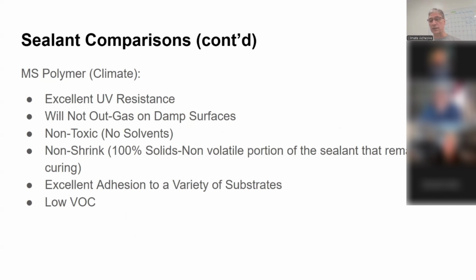So 100% solids just means the solids are just the part of the sealant that's left over after anything has evaporated off of it. And they have excellent adhesion to a variety of substrates. As we know with our products, concrete, masonry, glass, asphalt, a number of different applications apply, and they're low VOC.